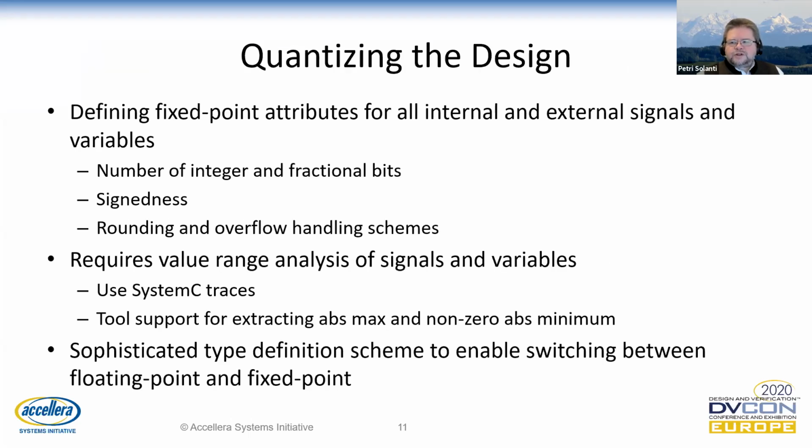Quantization is principally just defining the integer and fractional bits of the fixed point data types in the model. It is a well-studied area with lots of comprehensive academic studies. Yet, for most projects, a simple methodology using value range analysis and simple log2-based arithmetic is good enough. Fine-tuning must be done with simulation anyway.